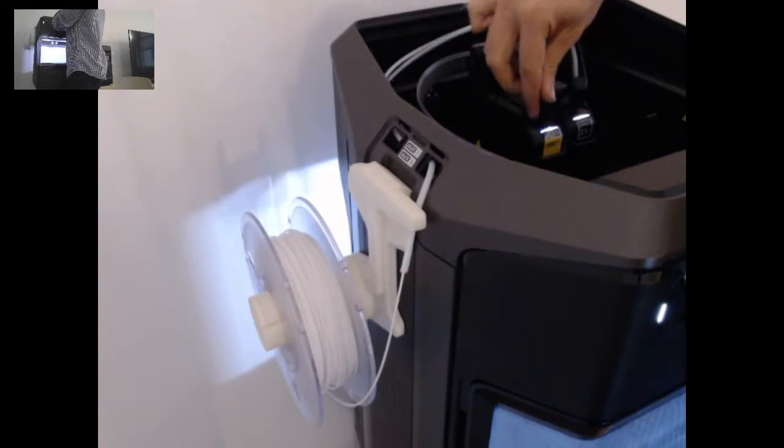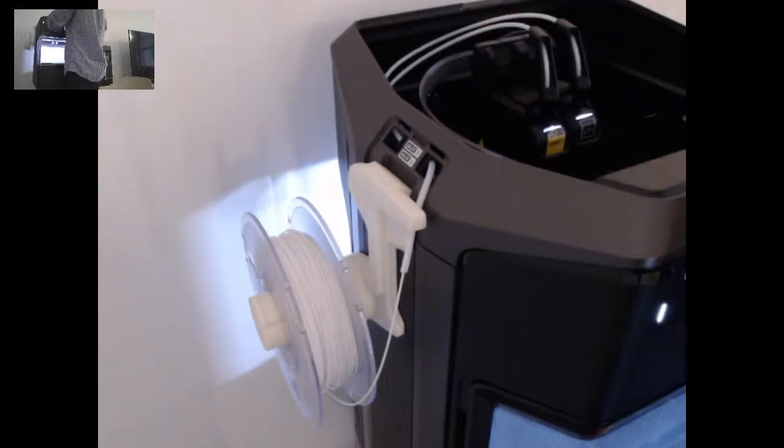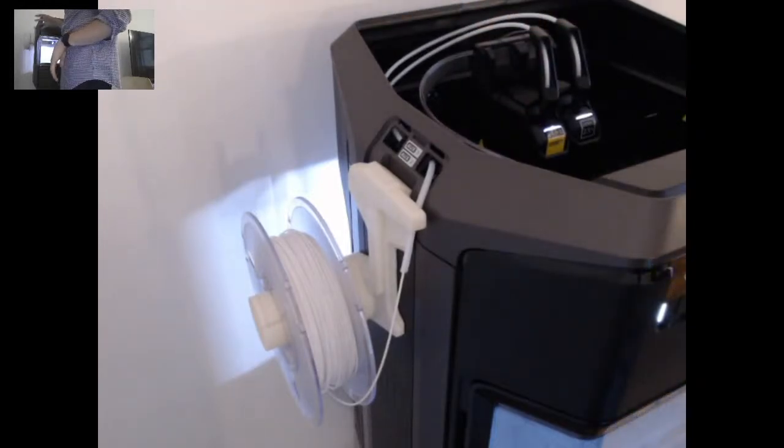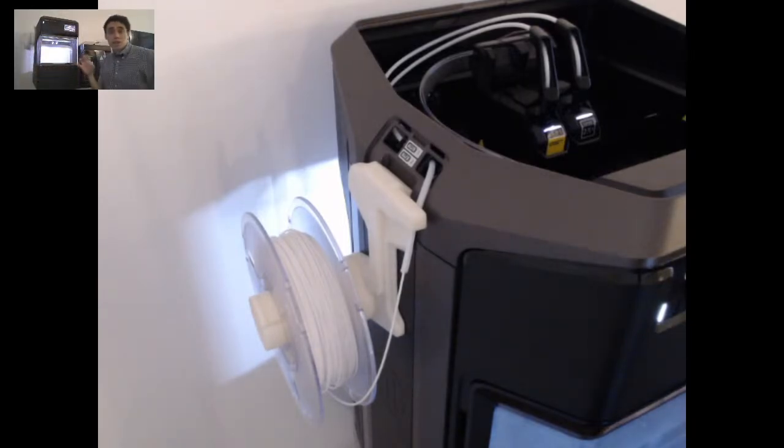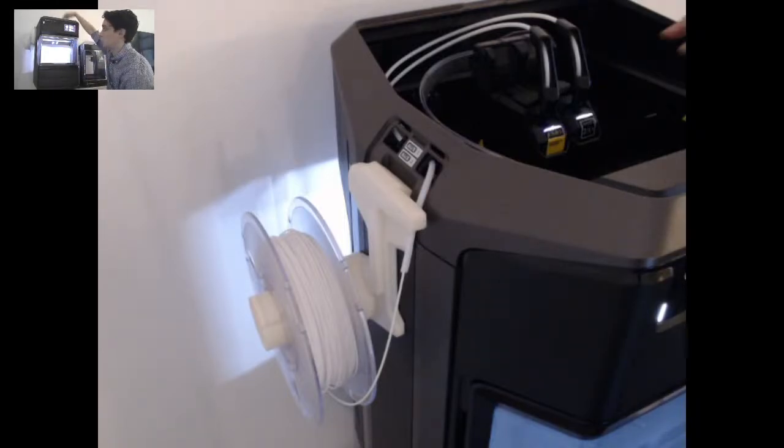There we go, placing my swivel clip again. The last step right now is to hit load on my printer so that I can actually see my material come out of it. Since my material is already making direct connection with the extruder, it's detecting it as already loaded. So instead of load, I'm going to hit purge on my printer.